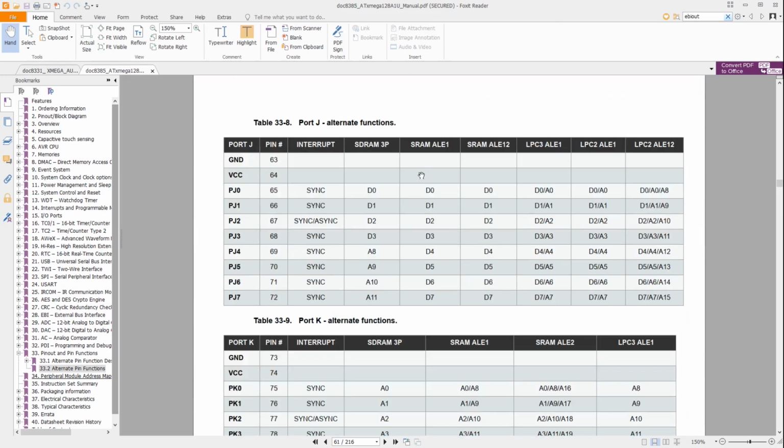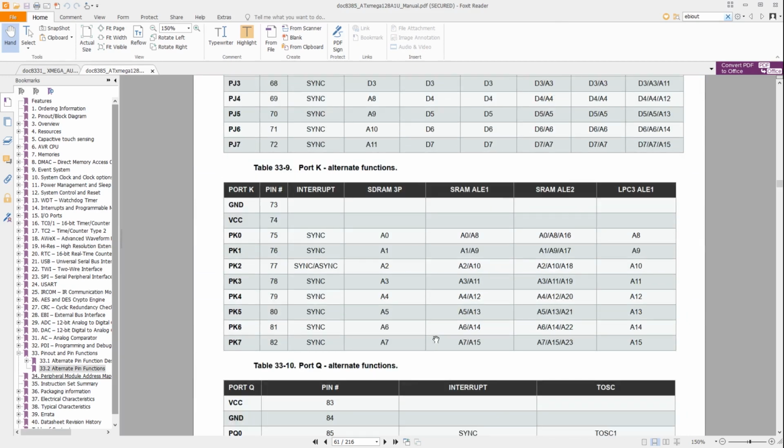Port J gives us access to the data bus, and port K acts as the shared bus in which address bytes 0 and 1 are time multiplexed. To summarize, I will do a simple example of adding an external 32K SRAM to the XMEGA using the external bus interface. Because I'm assuming no other external devices are currently connected, I can assume that I have the entire external memory map available, which would be from hex 4000 all the way to the end of the memory map.